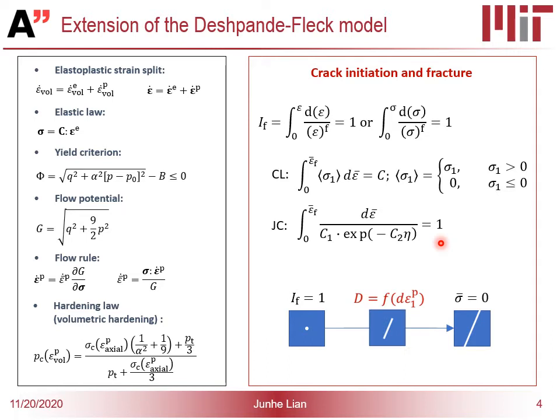That's why we made a modification to the model to introduce a term called damage evolution. The damage is formulated with respect to the maximum principal strain, as you can see here. In this case, the damage initiation criterion is what we have seen for those two criteria.